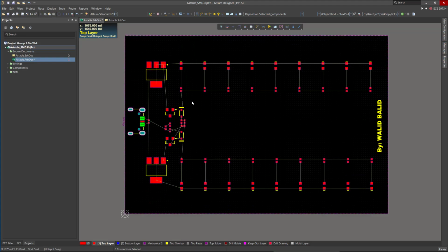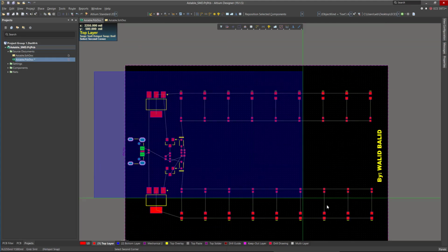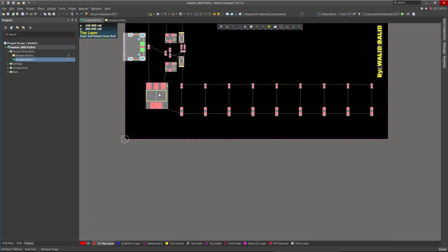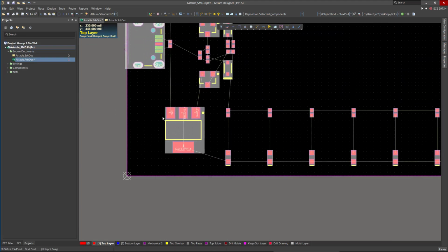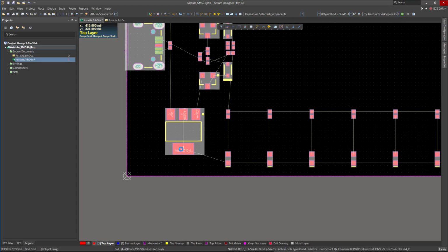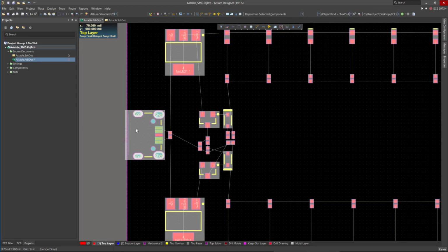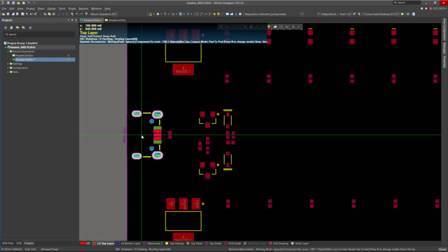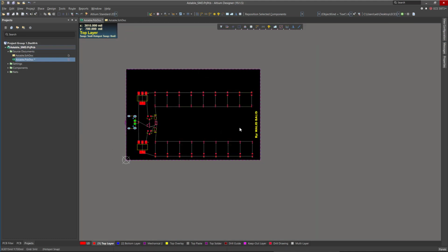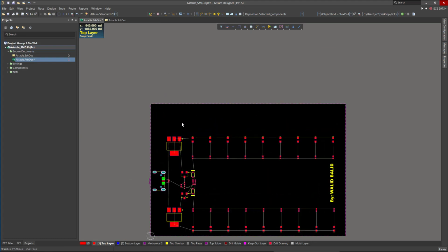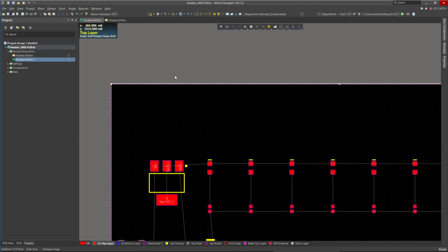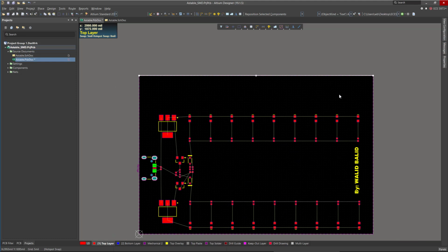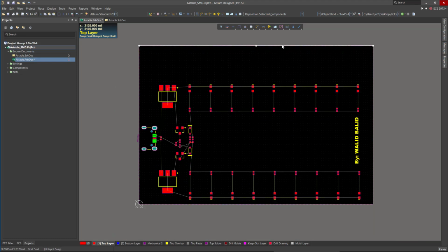Okay, this is good, just to practice how we can modify the board size. So we can move this also a little bit down. And this connector needs to be on the edge of the PCB in here. That's fine. And now we have the board outline from the old project, so we need to delete this one and create a new one since we are going to change the board size.